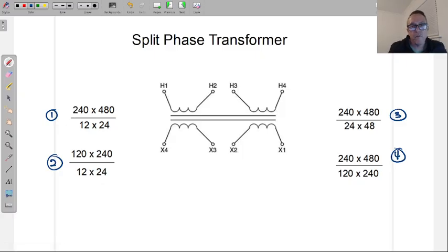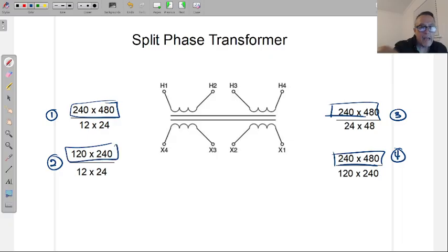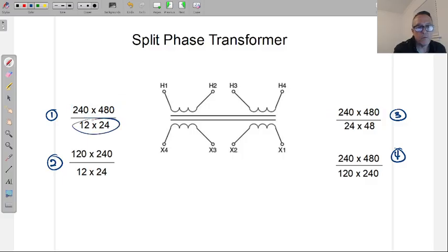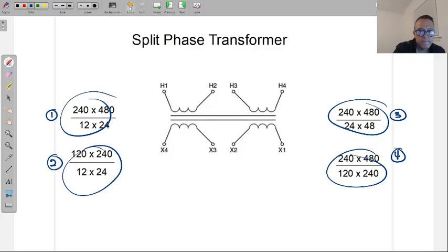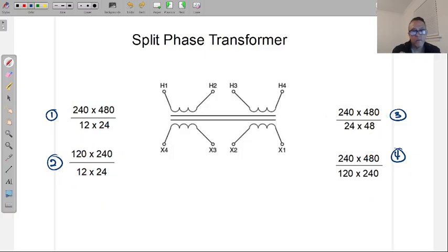So I have to now know 2 things about what I'm working with. I got to know what voltage do I have available nearby, because that will mean which primary side do I have to buy. And I need to know what voltage do I need on the secondary side, because that will dictate which one of these combinations that I need to buy. All right, so any one of these can function. Again, it's now application of, and so our examples are going to come with different ones to work with. So that's the first part to this.